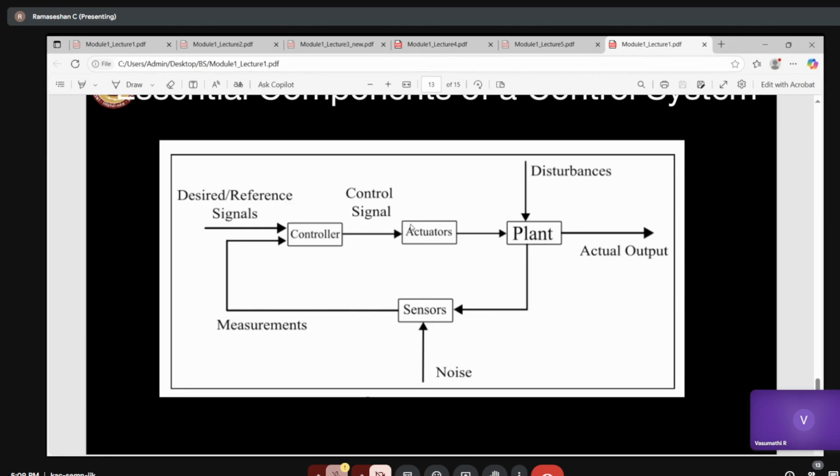If you're flying a quadrotor using a joystick, the actual actuator for the quadrotor is the voltage in the BLDC motors, but the control signal will be the joystick position. Now for us, if you want to drive a quadrotor without a human, then you have to measure all the states of the quadrotor, and based on that automatically compare it to the reference state, and then determine the joystick position automatically, or directly decide the voltage itself based on the measurement and the reference.